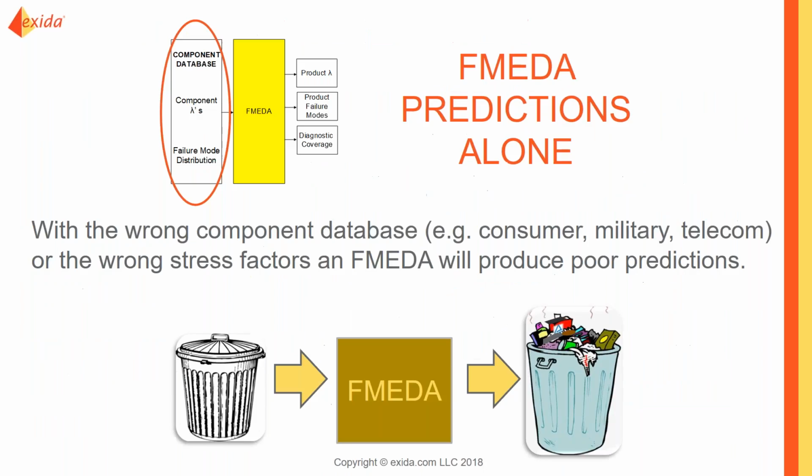Okay, so people say, look, Ted, that's all well and good, I know that they're good. However, I've seen some pretty bad FMEDAs where they've come up with really unrealistic numbers. And I'm going to say you're 100% correct, because I've seen those too. People say all FMEDAs are equal, and they're really not. What it comes down to is what database are you using? Because what you put into this FMEDA is what you're going to get out of it.